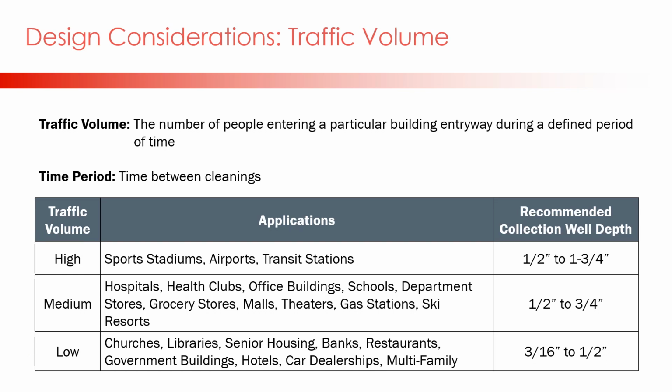One of the most common problems with entrance systems is that they become full of dirt or oversaturated and lose their ability to retain the dirt. So determining the right size entry flooring for a building is a must.